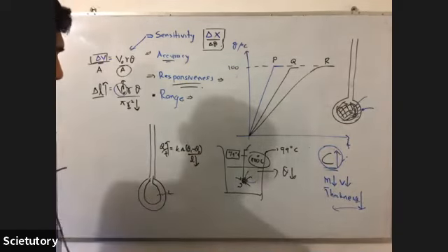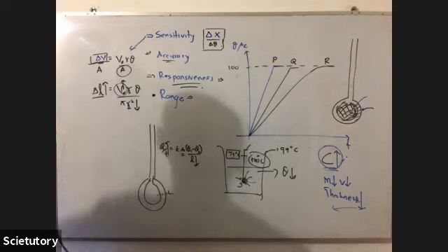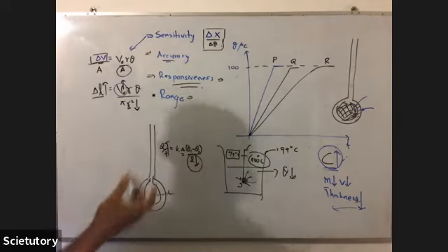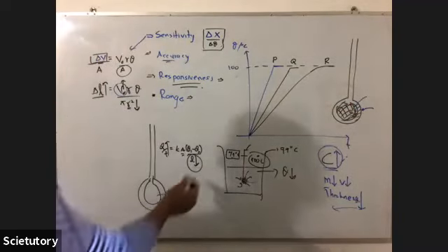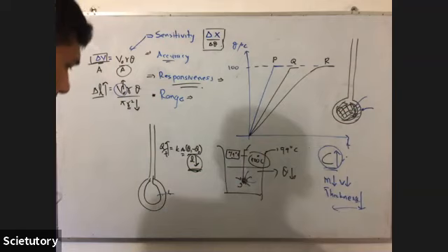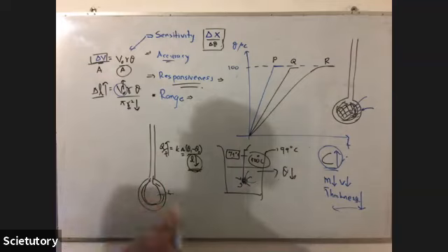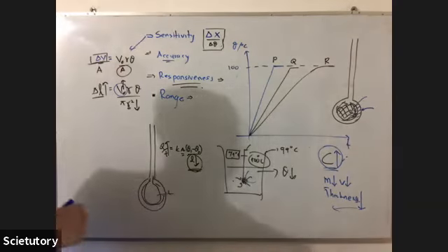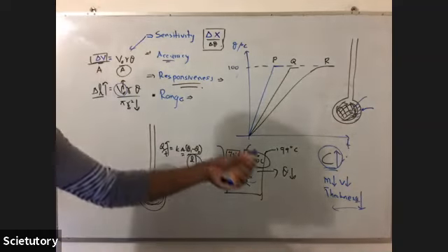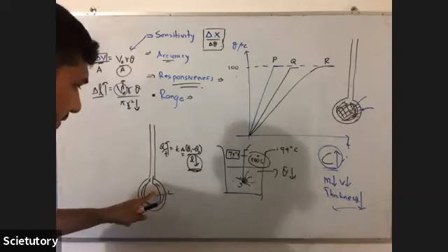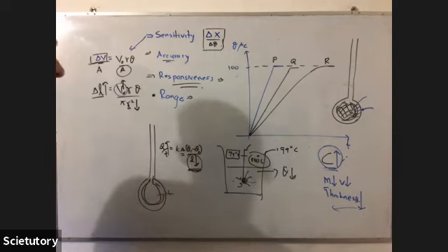Okay, you understand? Usually you don't change the A. A is not much changed because A is needed. A is fixed because that is determined by the volume of this bulb, but the thickness is changeable. So you reduce the thickness as much as possible, so that if the temperature of the substance being measured changes suddenly, the change is transferred to the mercury very quickly when you have a very thin wall.